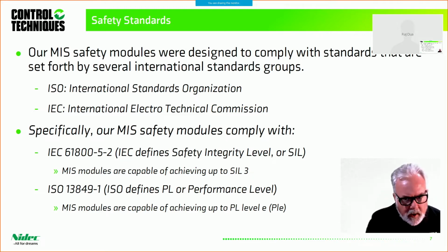Specifically, our modules comply with IEC 61800-5-2. Now, IEC is the regulatory agency that is going to define safety integrity level, or SIL. If you've used our drives, our M700 drive, for example, our high performance drives, or our Commander C300, either one of which, those are designed with safety in mind. Our Unidrive M702 and the Commander C300 are designed to achieve SIL level 3.